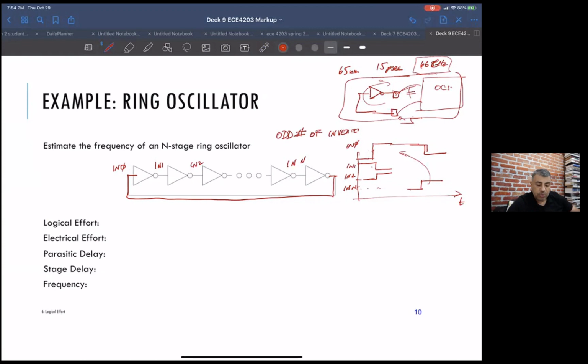But if you have a ring oscillator, in a 65 nanometer process it might be oscillating at 1, 2, 3 gigahertz, something like that. And as you'll see, because these are all the same type of device, you can calculate back the delay of each individual inverter with a lot of accuracy. So you can use this to make sure your process is where you expect it to be.